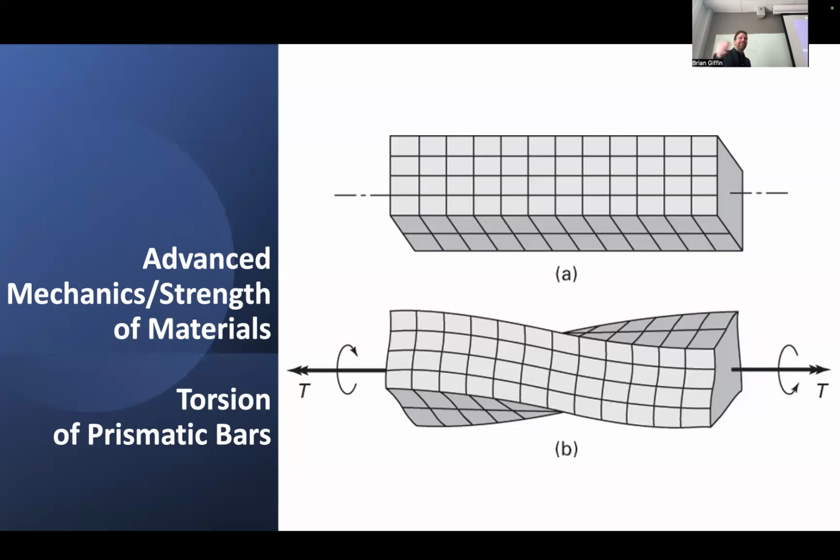And even if you didn't have that due to transverse loading, you could still have, let's say, relatively long shafts to which you're applying some kind of end torques. So twisting things. And that torsional moment, torque, is really characteristic of this phenomenon of torsion. So torsion, really looking specifically at this case of just beams subjected to these end twisting moments and end twisting deformations, can be analyzed again through the more general lens of the theory of elasticity.